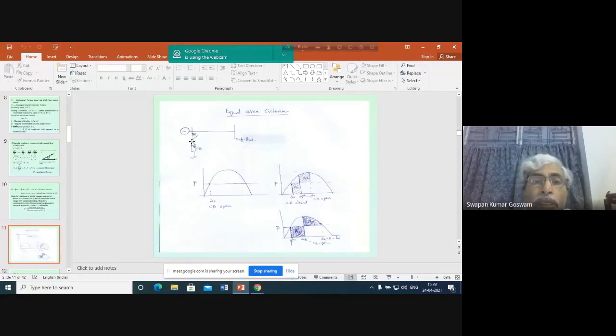Okay, so when the circuit breaker was closed and connected at the terminal of the generator, it means that it is short circuited. At the terminal of the generator, a short circuit fault has happened. Because of the short circuit fault, power output becomes zero instantly. Initially, this much was the power being delivered by the generator, and this was the operating point. As soon as the circuit breaker is closed, output becomes zero, and we have assumed that after some time the circuit breaker is opened again.